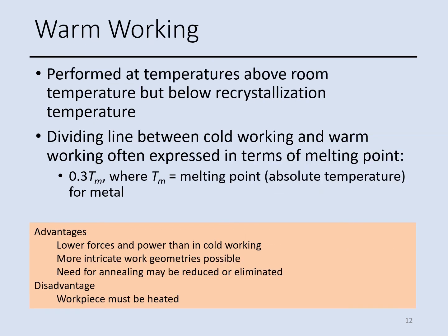The next metal forming process, considering the temperature, is called the warm working process, which is performed at temperatures above room temperature, but below the recrystallization temperature, where new grains can be formed. This temperature is a function of melting point.